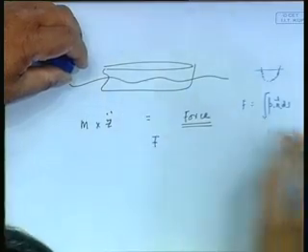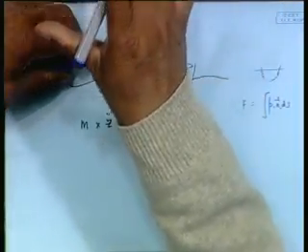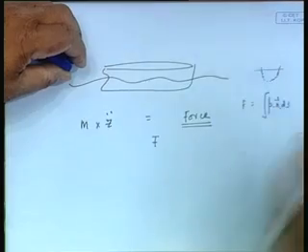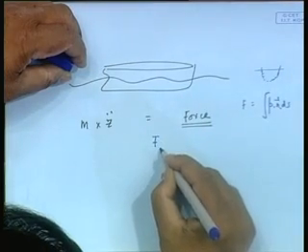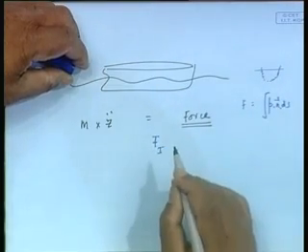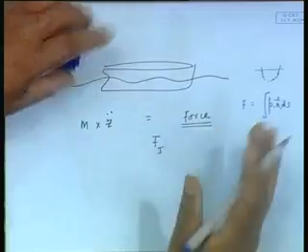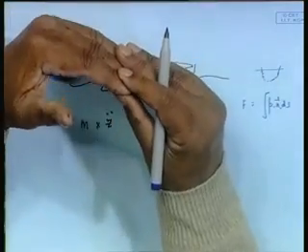Now this pressure has two components, but I am talking of the dynamic incident wave pressure. So I end up getting the incident wave force, I am calling this Fi. In principle, this would be the force arising because of the incident wave pressure at those locations. That is rho d phi by dt, where phi is only phi I. Why phi I? Because we say that the body did not disturb the waves.